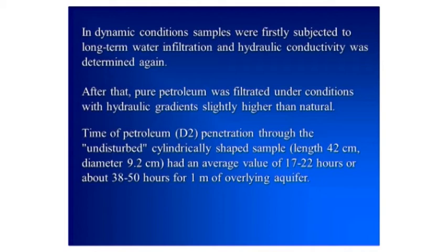Time of petroleum D2 penetration through the undisturbed, cylindrically shaped sample had an average value of 17 to 22 hours, or about 38 to 50 hours for 1 meter of overlaying aquifer.